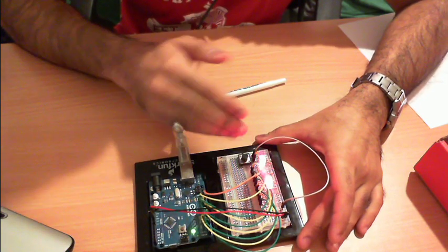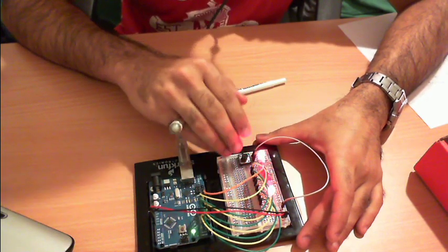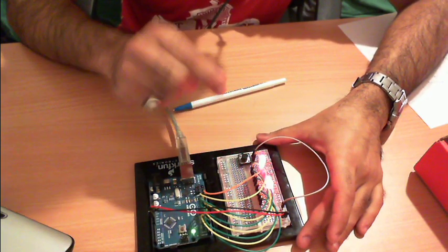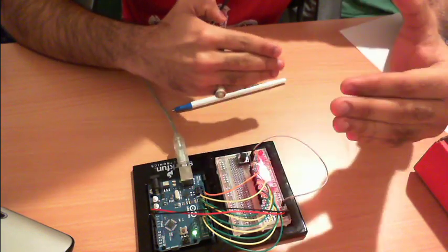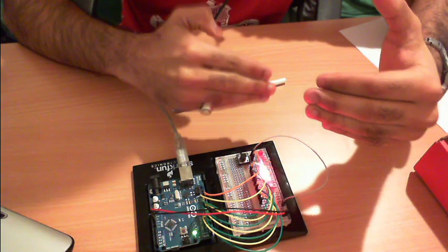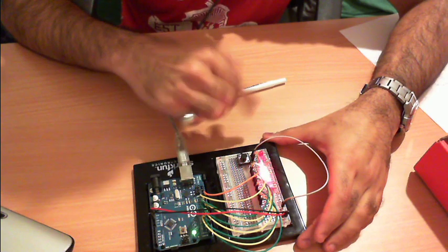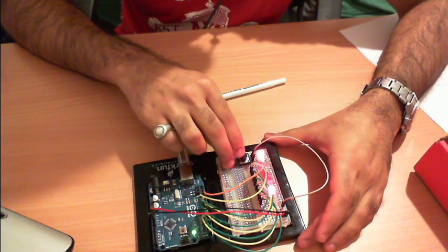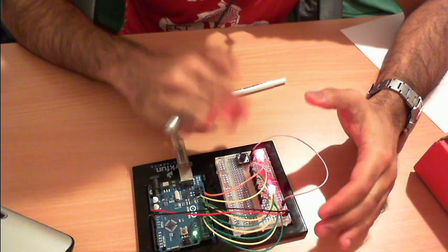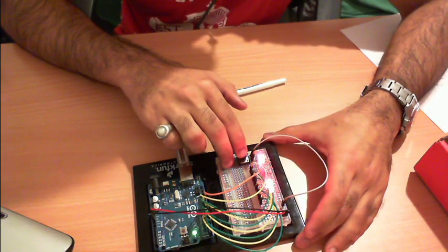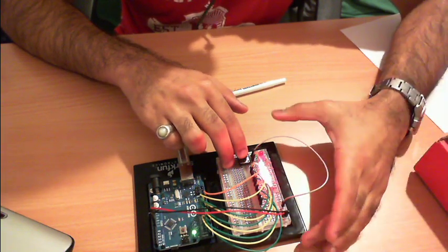Initially I couldn't understand why this was the case, but then I figured out that it's because of all the different delays in the loop, because they tend to add up, like between each of the LEDs blinking, so that makes the button less responsive. So generally with most of your programs where you have a delay in between, pressing the buttons is going to be a bit less responsive than it would if it was just a program where there was no delays.